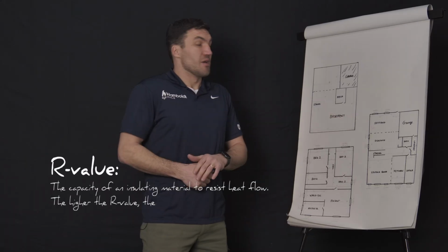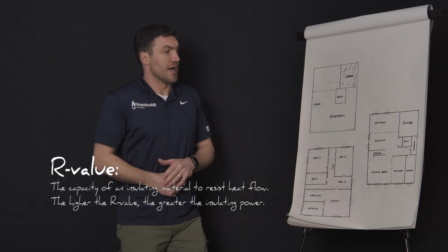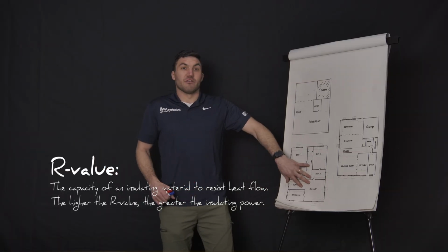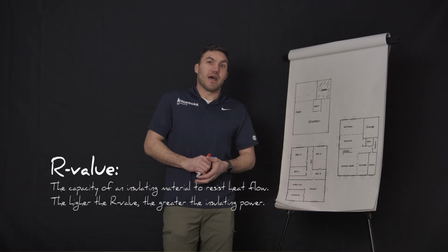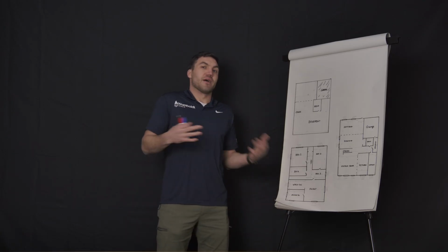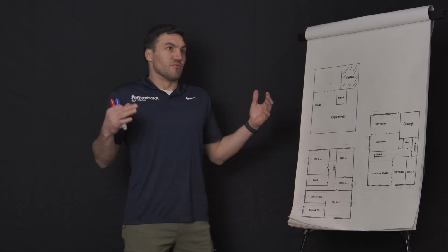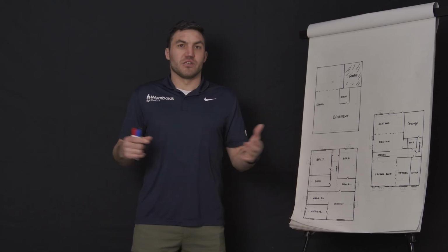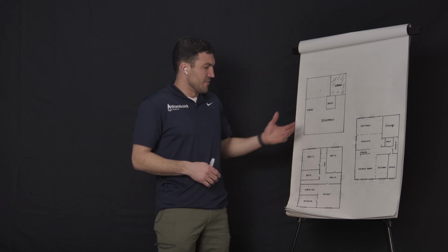Maybe you know that, maybe you've done upgrades, maybe you have changed your windows lately and you have some data on that. I'm also gonna get what is the R value in your attic. Again, maybe you've had that done recently and you have that, but if you don't, we can kind of refer back to the Ontario Building Code to get the best idea of where your insulation is based on the year your house was built.